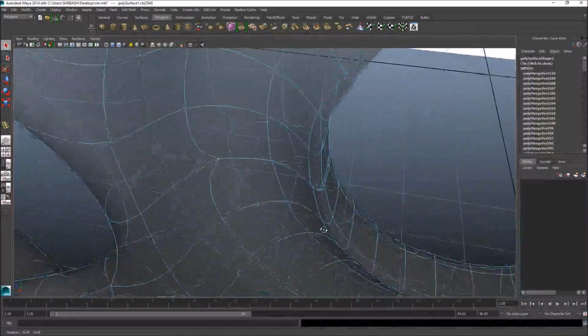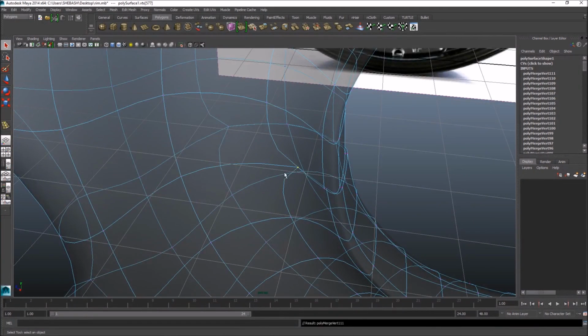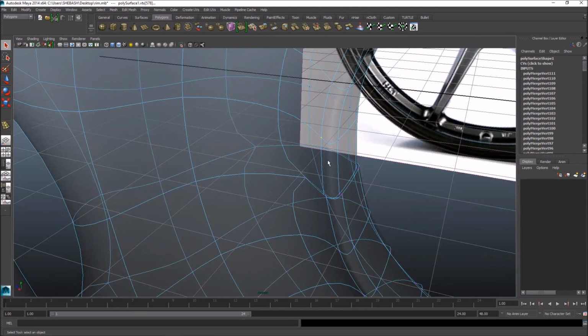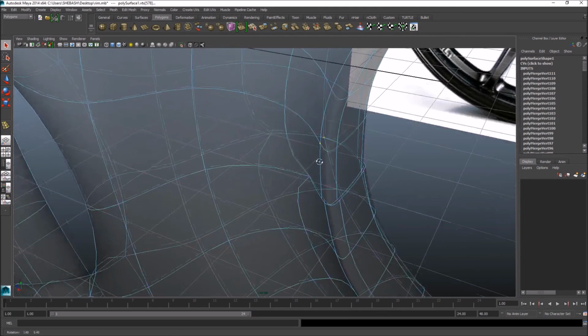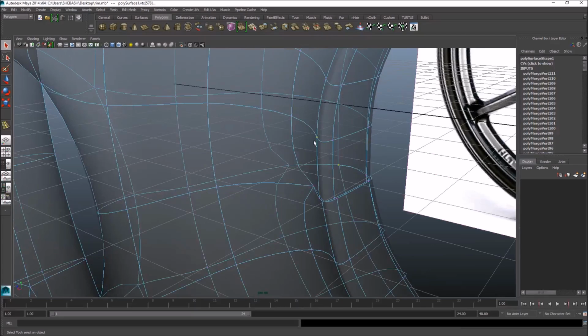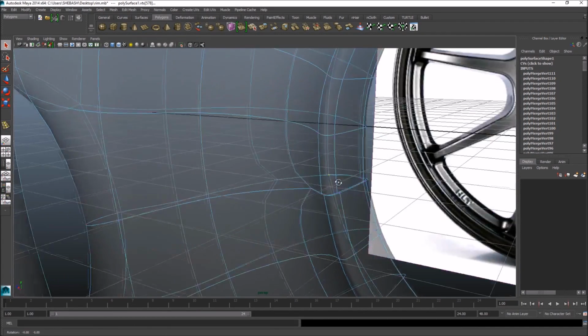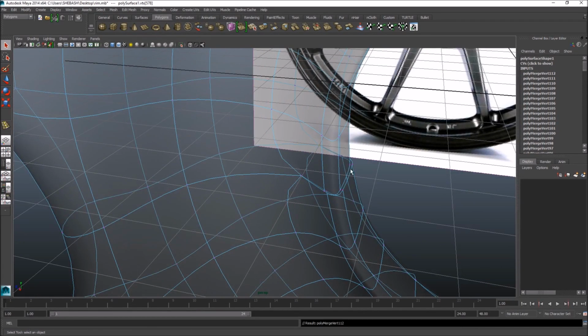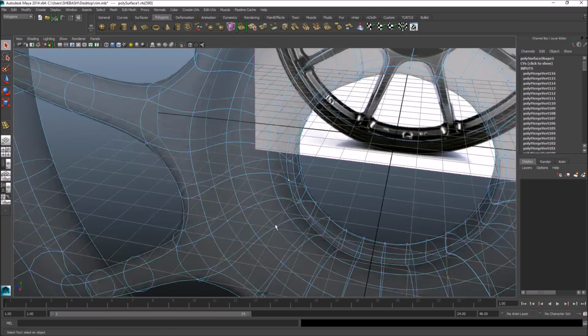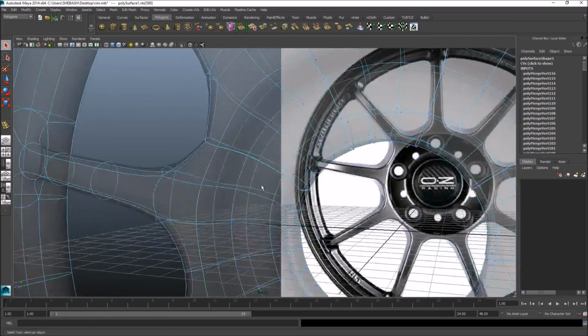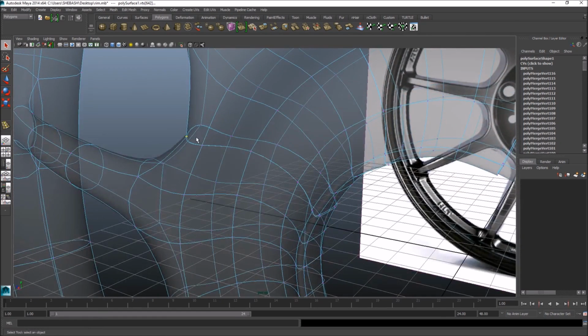Yeah, while you are doing this, it might be useful to rotate the camera from time to time, so you know you are not grabbing, like for example this, I'm grabbing a vertex I do not want to merge, so it's just to make sure that I'm selecting only the stuff I want to select. You just rotate the camera and make sure.